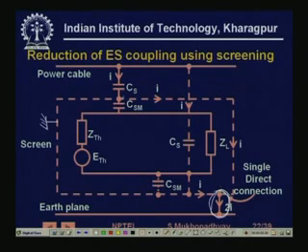So these capacitances are independently connected to ground. You have this connected to ground, you have this capacitance connecting to ground, and correspondingly you also have these connected to ground. So the voltages here do not cause any voltage in these signal lines. This is the principle of screening.